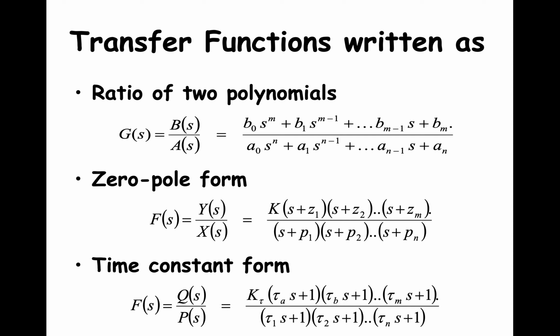The a's and b's are the polynomial coefficients, and m's and n's are the powers of s included in the equation. The expression should be written in a way that m, the highest power of the numerator, is less than n, which is the highest power of the denominator. If m is not less than n, then you must use polynomial division to remove some terms and produce a ratio term where m is less than n. You will rarely be doing polynomial division in this course.